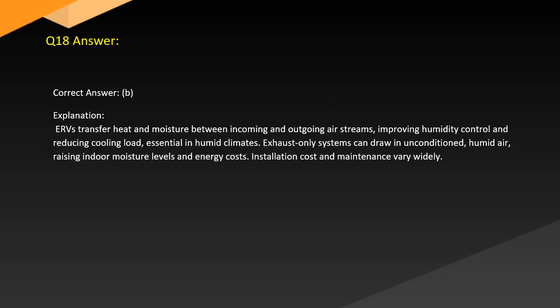Answer. Correct answer: B. Explanation. ERVs transfer heat and moisture between incoming and outgoing air streams, improving humidity control and reducing cooling load, essential in humid climates. Exhaust-only systems can draw in unconditioned, humid air, raising indoor moisture levels and energy costs. Installation cost and maintenance vary widely.